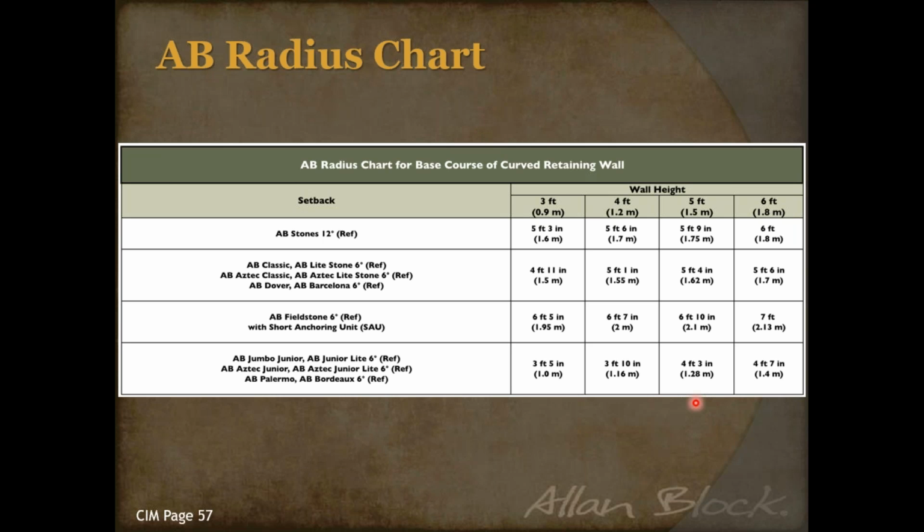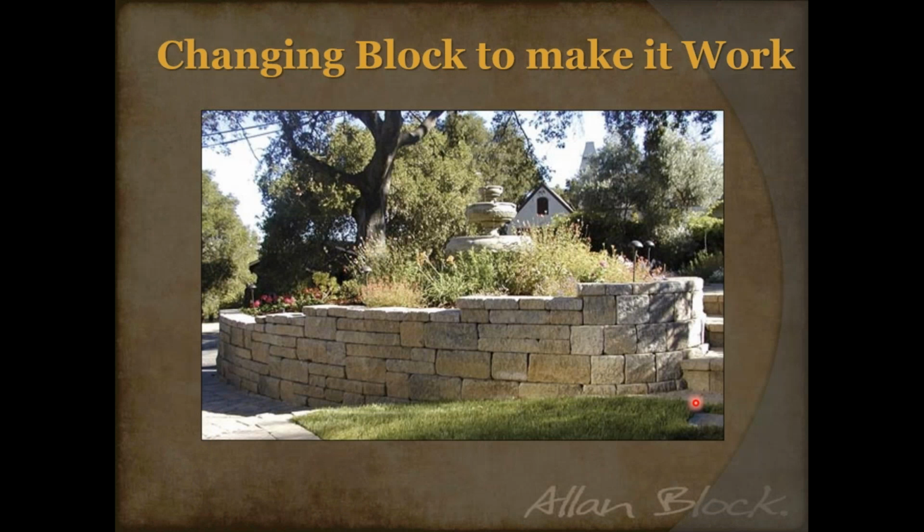I know a lot of contractors that try to keep most of their radiuses around that 10-foot mark. Part of it is then it's consistent, it looks nice and fluid, and they don't have to worry about the blocks kind of pinching up on them towards the top of a wall, because that 10-foot minimum radius would actually kind of feather it out very nicely. But it's important, like I said, understanding the products.